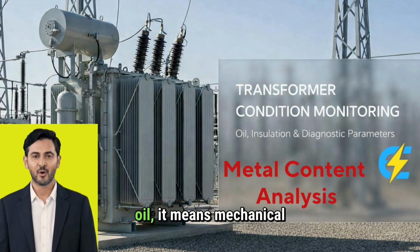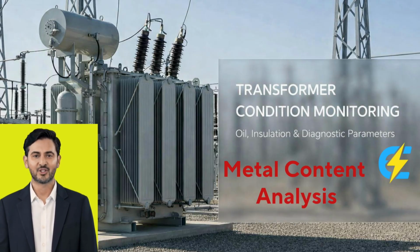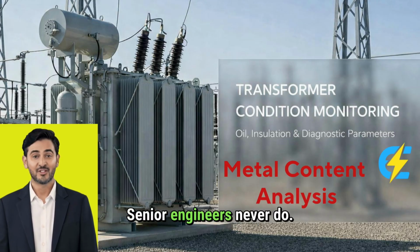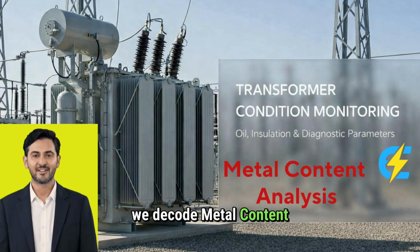When metals appear in oil, it means mechanical wear, corrosion, arcing damage, or insulation breakdown has already started. Most engineers look at metal results and say, values are small, ignore. Senior engineers never do. In today's Electroverse episode, we decode metal content analysis in transformer oil.